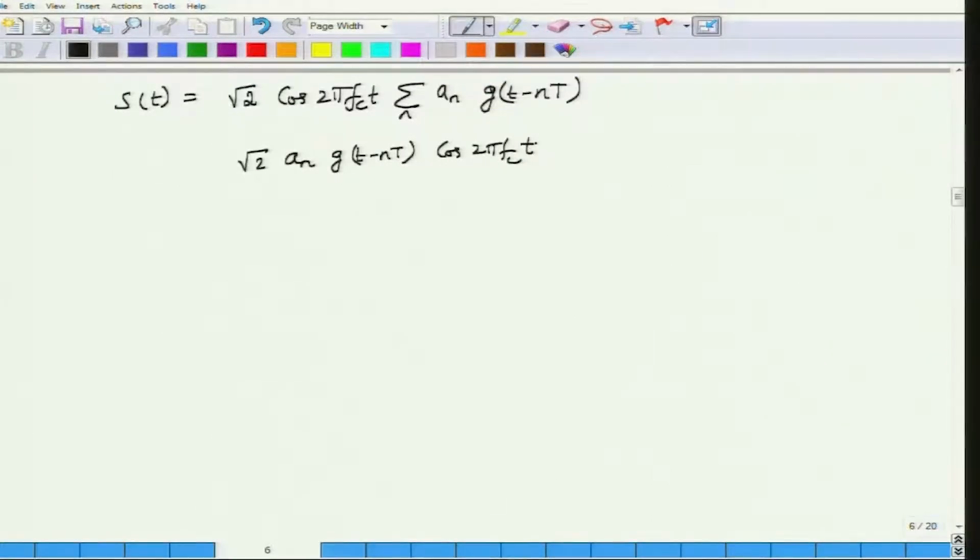It turns out that if you look at the spectrum of this, you will see a spectrum centered at f_c. This spectrum will be symmetric about f_c, with the spectral shape determined by g(t). What you can see is that the information contained in both sidebands is completely redundant. Whatever the upper sideband is telling you, its mirror component is the lower sideband. So why do I have to keep two sidebands in order to convey information?